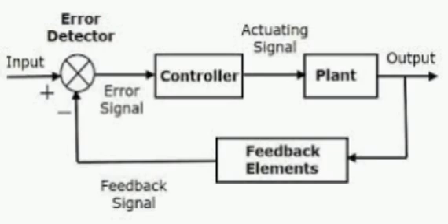For step input, steady state error for different types of systems: Type 0 means step input a by 1 plus k. Type 1 step input 0. Type 2 step input 0. For ramp input, type 0 infinite, type 1 a by k, type 2 0. For parabolic input, type 0 infinite, type 1 infinite, type 2 a by k, where k is the system gain.